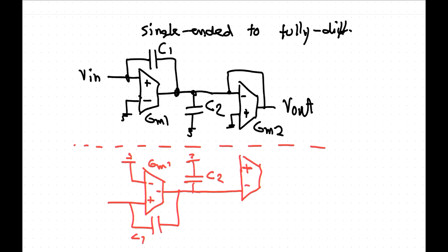What's the role of the positive feedback C1? That C1, it's just another filter. It puts in a zero in the transfer function. If the current flows in that, or it puts in a parallel path, so you've got current flowing both in this way here and also out there, so it adds extra current, but it becomes a zero in the transfer function.